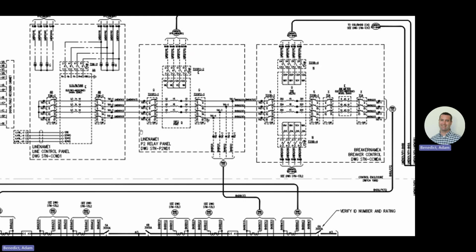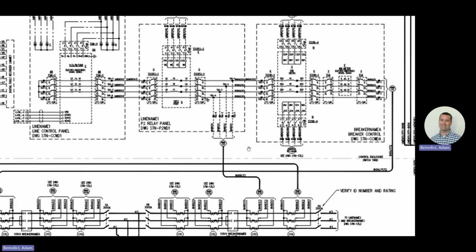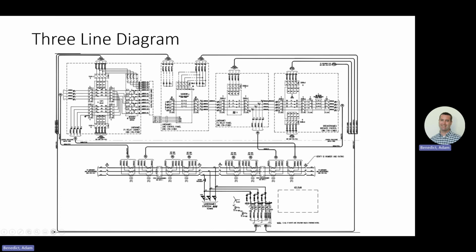And then this would be your line relay. So they're summing basically this current and this current to add up to this line. But this breaker relay only cares about the current coming out of here. So that's where you have to really look at it. What does this relay need to see versus this one? This one doesn't want both. It's only looking at this breaker. So it goes through, and then this line relay needs both values. So that's where you would parallel those up.